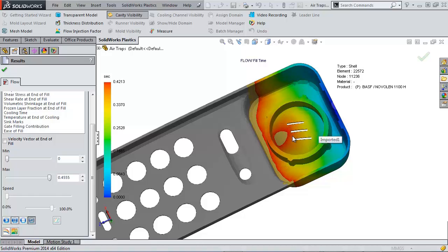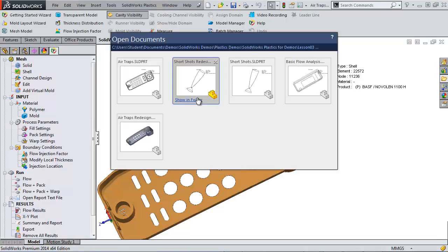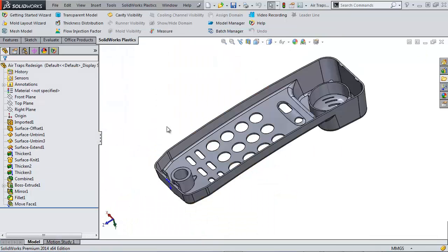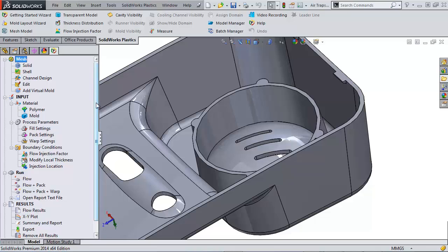Well, that pocket is going to have a dieseling effect and create a burn mark because that air is compressing until it combusts. So we do not want that in our plastic parts. So we can look at our design a bit and figure that if we have a thinner wall here that's more similar to this outer one, then hopefully we shouldn't have as much of an effect of the slowdown.